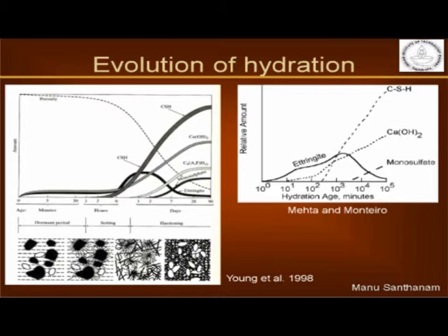So as the setting progresses, as hydration progresses, more and more of the space gets filled up and you ultimately get a space that has very little void content. You have occupied almost the entire water filled space by the hydration products, because of which your strength continues to go up, and that strength going up also corresponds to the CSH which continues to go up. As CSH is going up, obviously your calcium hydroxide also has to go up, because that's another product of the hydration of your silicates with water. So calcium hydroxide goes up, calcium silicate hydrate goes up.